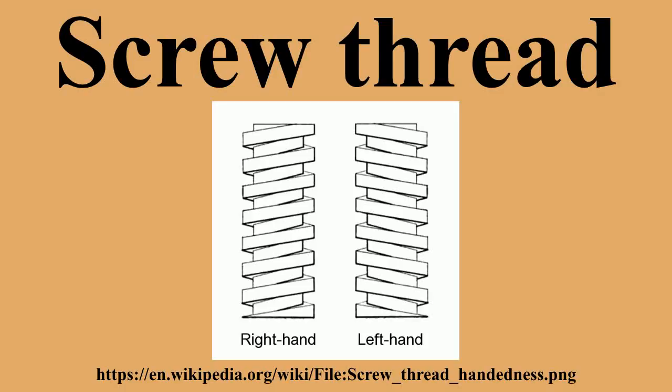Knowledge of PD determines the position of the sharp V thread form, the sides of which coincide with the straight sides of the thread flanks, e.g., the crest of the external thread would truncate these sides a radial displacement d2 away from the position of the PD line, provided that there are moderate non-negative clearances between the root and crest of the opposing threads, and everything else is ideal.